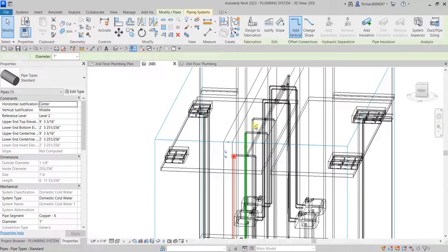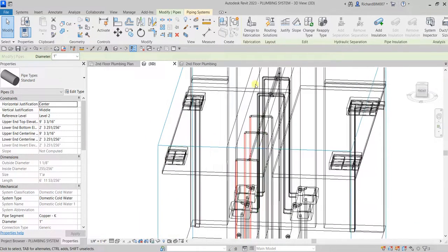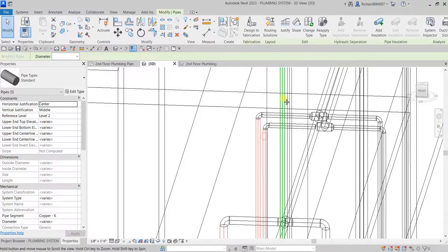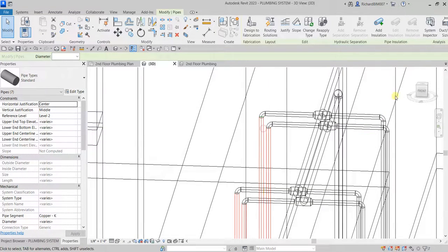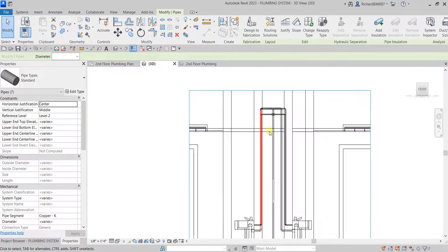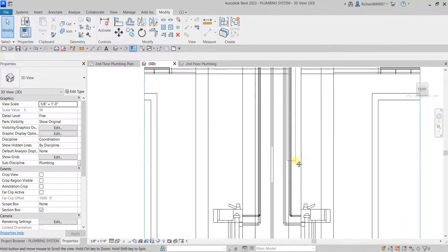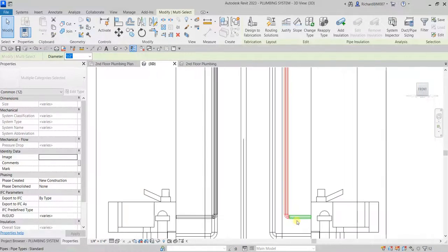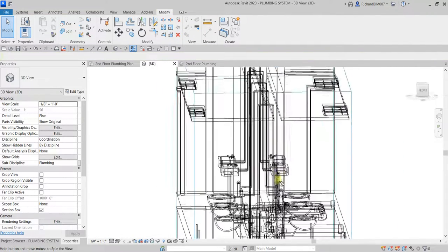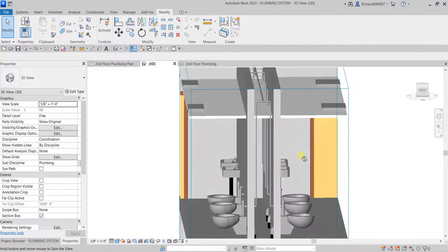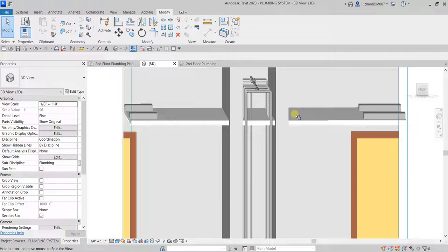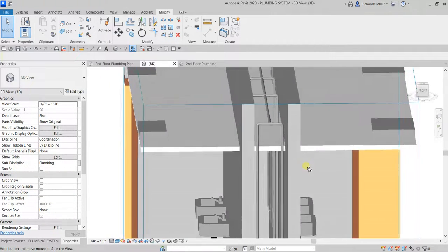Click, hold control. Make sure you're holding control so that you are selecting multiple pipes, and then go to the front, and then you can use the arrow on the keyboard to move it, right? Okay, so let's select. So you can do this technique, so you can also make it selection like this one. Okay, and then use the arrow on the keyboard to move it, and then you can type SD for shaded view. There you go, right? So those are just some of the modeling techniques that you can use.